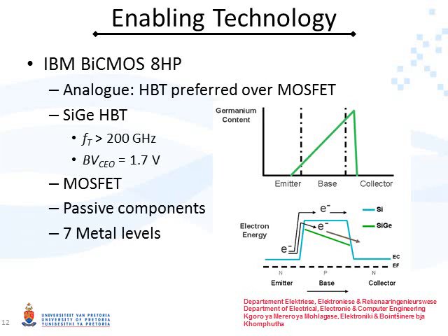The Process Design Kit, or PDK, comes with a full library of passive devices. These include resistors, capacitors, and spiral inductors. The PDK also allows additional passive devices to be constructed, such as transformers, which can be used as a power combiner to increase the output power of the power amplifier.